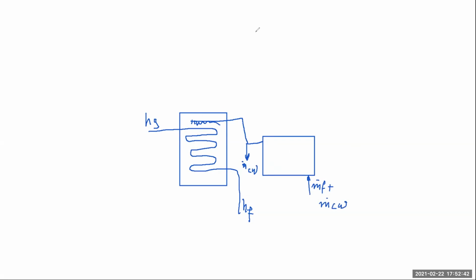And the vapor is going to leave from the top here. The enhancement that we are going to do here is we need to increase the PR of the system. PR is simply m dot distillate divided by m dot steam. In order to increase the PR, I can either increase the distillate or decrease the flow rate of steam that we have. And what we are going to do now is work on reducing the m dot steam.